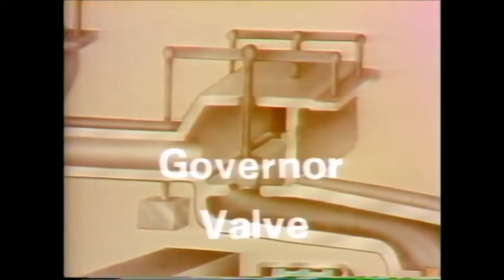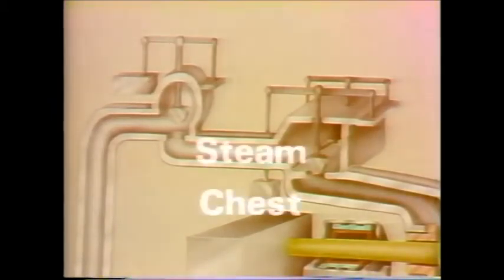Now, for this reason, control valves are sometimes called governor valves. Under normal conditions, the control valves are partially open to regulate steam flow during operation. Depending on the turbine design, steam may flow from the stop valves to the control valves through a system of pipes, as you see here, or through a large area designed to hold steam called a steam chest.